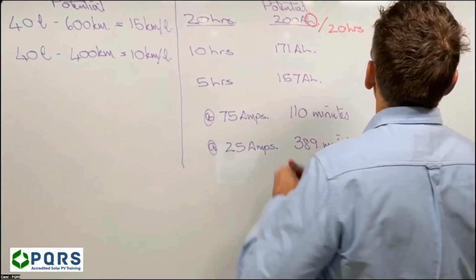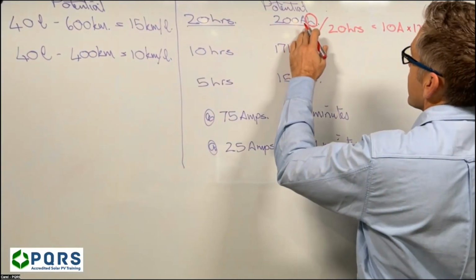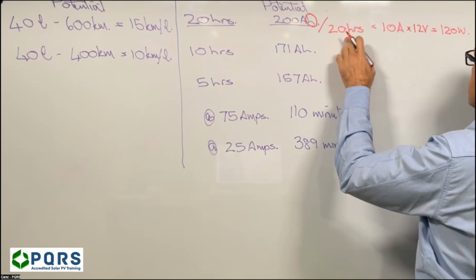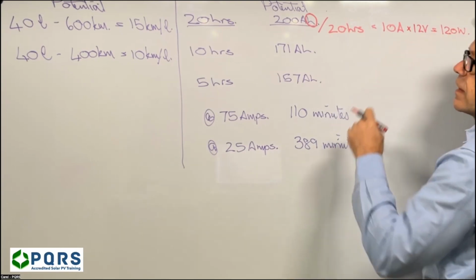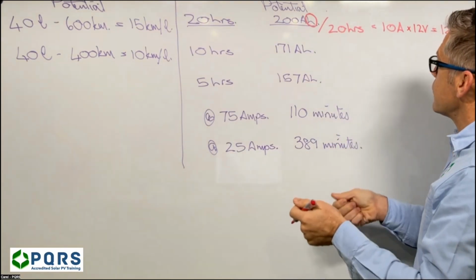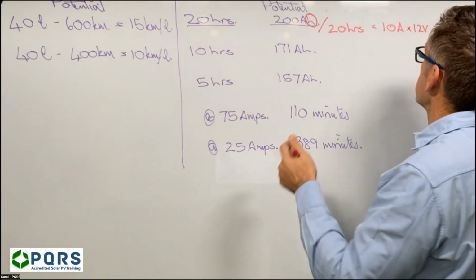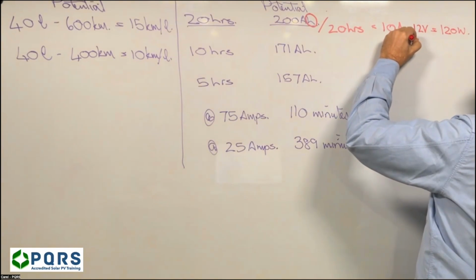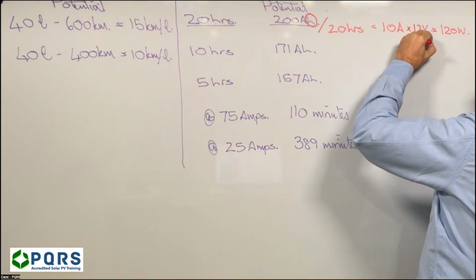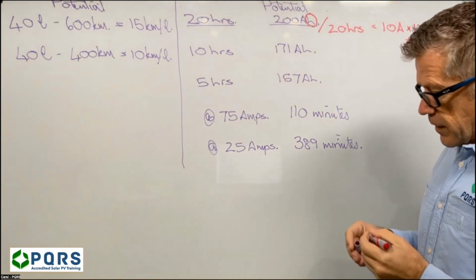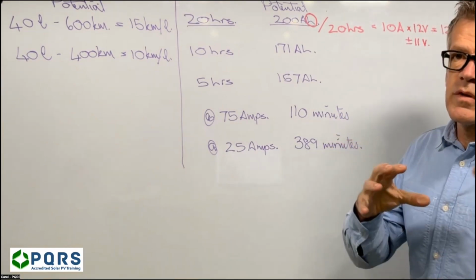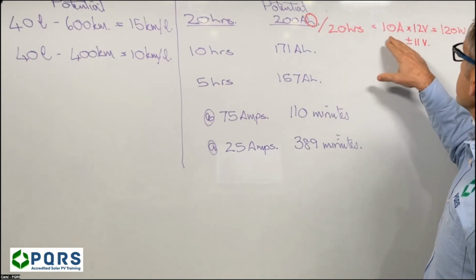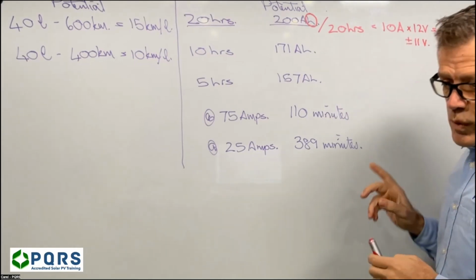So what these guys are saying is that once we have discharged this battery over a period of 20 hours at a rate of 120 watts, we take a multimeter and we measure the potential voltage over the cells or over the 2 terminals, we'll end up with plus minus 11 volts. So this, according to the data sheet, means the battery is completely discharged. So that gives us 120 watt discharge rate.